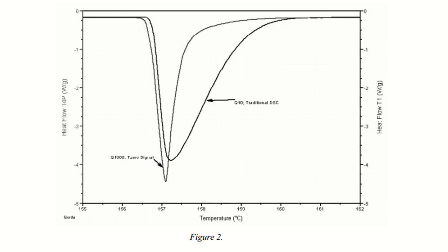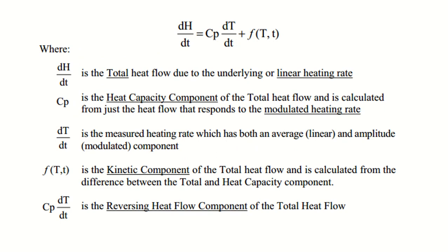Moreover, calibration factors are measured versus temperature and then continuously applied to the four-term heat flow equation, which helps us to calculate the sample heat flow. We have already discussed this formula to measure the total heat flow, which is due to the underlying or linear heating rate.